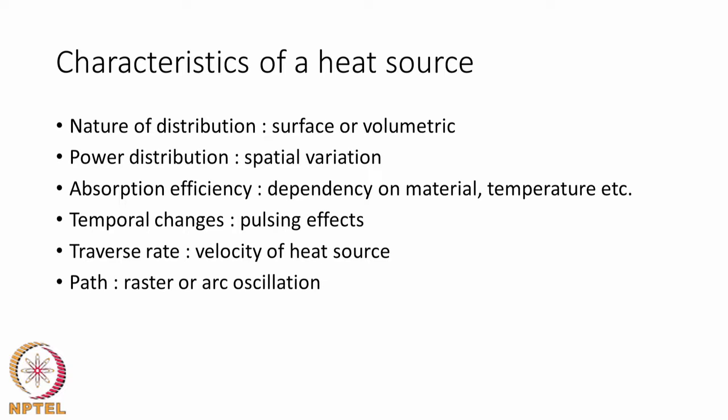Oscillation also can come in reality. For example, magnetic arc oscillation is sometimes used to avoid centerline cracking, and therefore, we may also want to look at whether the heat source is moving in an oscillated manner across the path during the welding process. So, we need to observe all these quantities and then capture them in the model that we are choosing to represent the heat source.